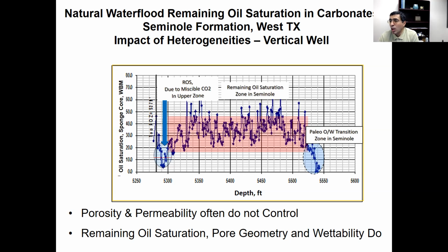And the last question: what do you think of hybrid gas surfactant flooding or huff and puff for unconventional reservoirs? Huff and puff has potential. By huff and puff, you mean gas and then water, or that's WAG? Or gas and surfactant slug, what do you mean? Well, gas injection overall is challenging. For the gas injection that is most suitable, the gas has to have very close composition to the oil in order to form miscibility.